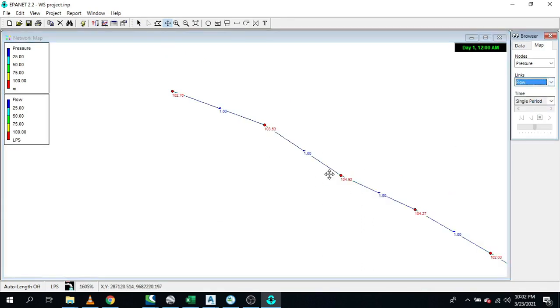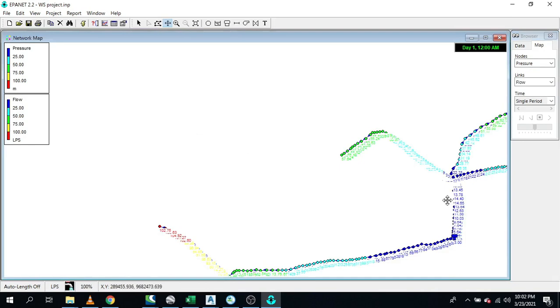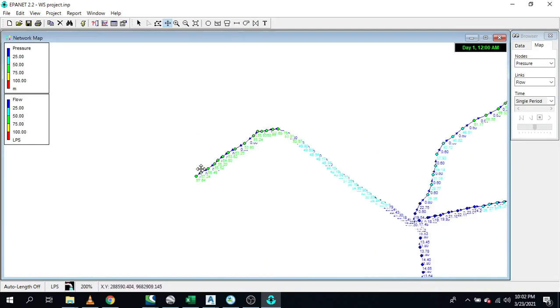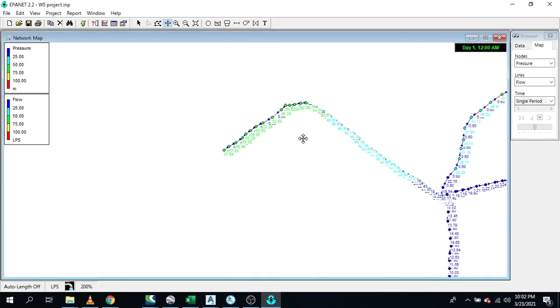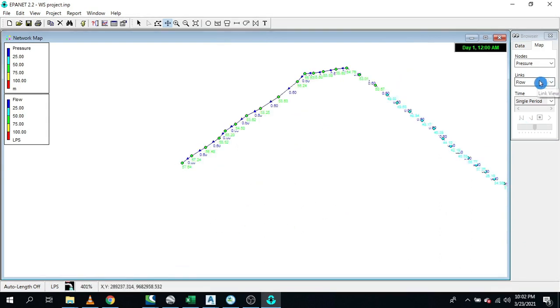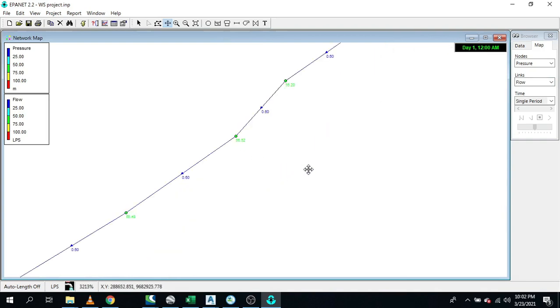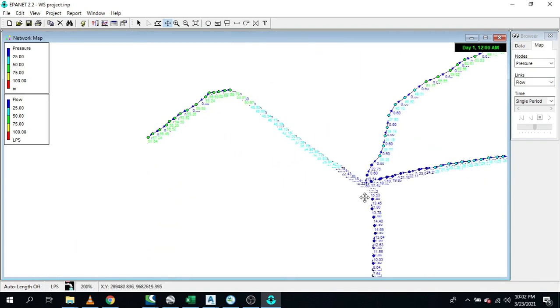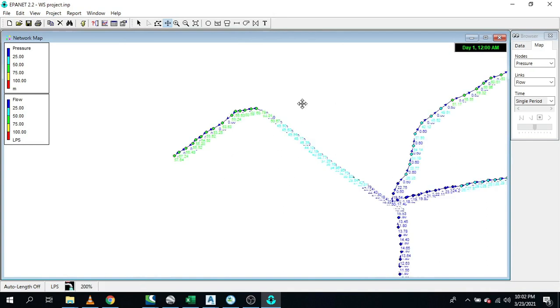0.9 flow here is 1.6 liters per second. 1.6. Okay, and again let's check here again. Let's check in this branch. This branch 56 with a flow of, our flow here is 0.6. Now we need to reduce again. Let's try to reduce this portion here and see if we can reduce the pressure from 56 at least to 20, around there.